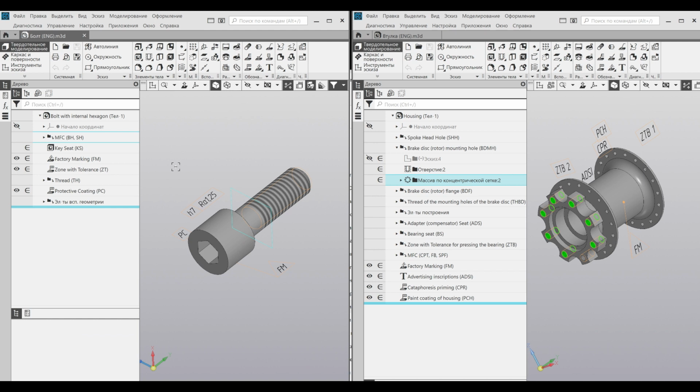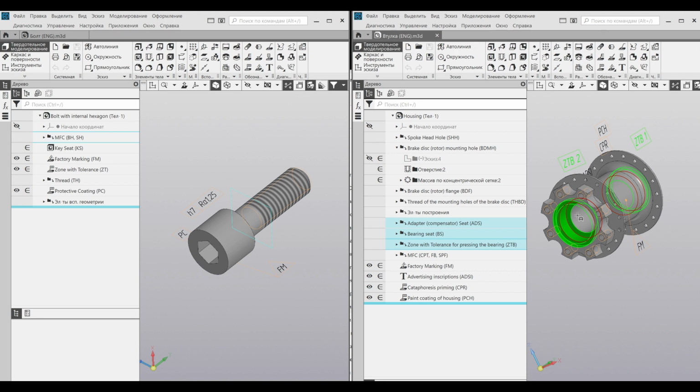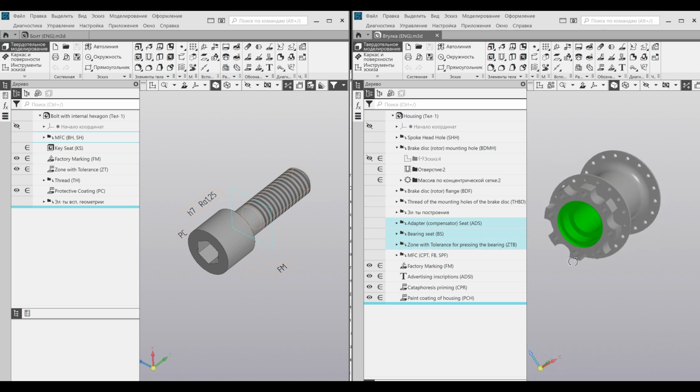The front wheel bushing is firstly a component with a low potential and low reduction model. This concept will be discussed by us in issue number 18, Cost Driver Model Visualization, Cost Reduction Action Plan for Object of Analysis. Secondly, a component whose design is formed mainly through evaluation and practical testing of the design of the front wheel of a bicycle, and not by methods of value design engineering, i.e. at the dawn of bicycle construction, there was just a bushing which had the purpose of placement of bearings and the transfer of load from spokes and axis of rotation.